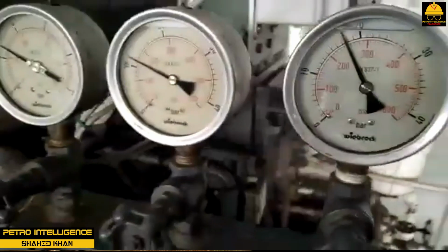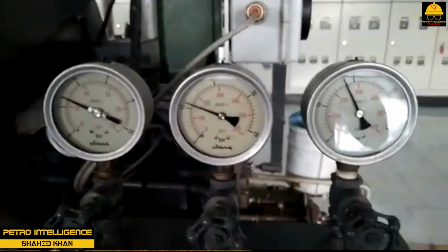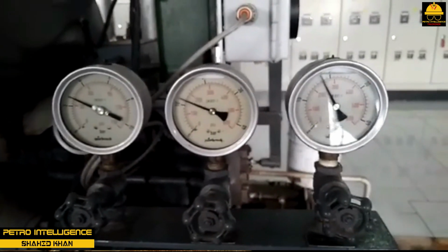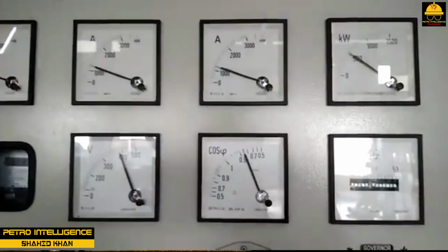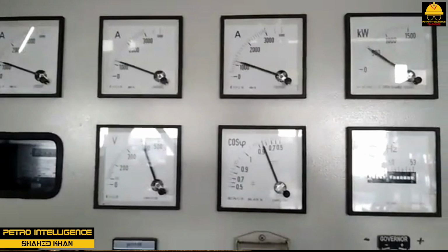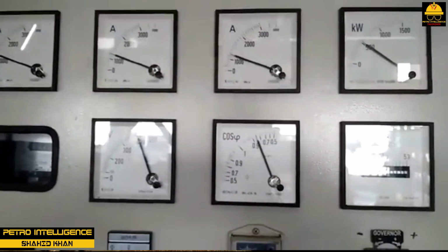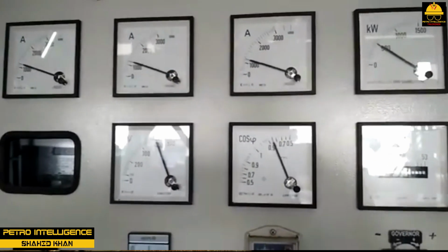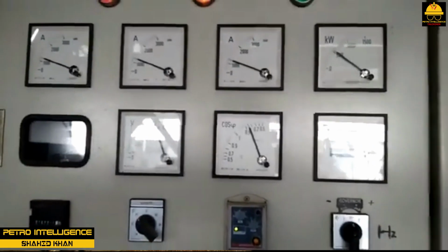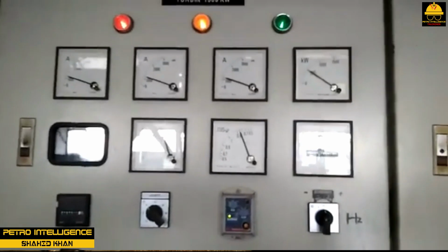Steam turbines are designed to be operated at a controlled speed. If the steam turbine is operated above or below the normal operating set point, a problem known as hunting may occur. Hunting takes place when turbine speed fluctuates while the controller searches for the correct operating speed. Another problem that causes the steam turbine to speed up and slow down is mechanical linkage binding.